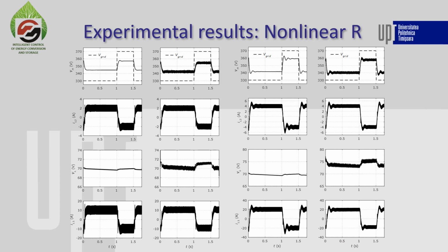With this method, the same voltages are achieved during the two regions, with the difference that for the second method, the current and voltage oscillations are greatly reduced. And of course, a smoother transition is achieved. Therefore, we can conclude that the nonlinear resistance method does not introduce the same oscillations during the transition between the charge or discharge modes.